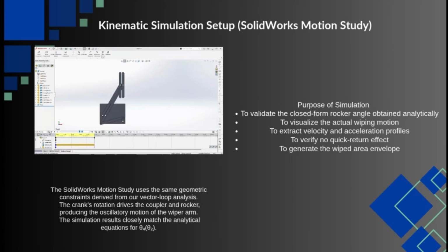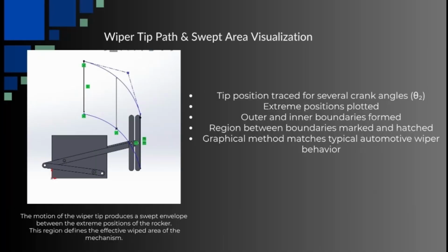The purpose of simulation is to validate our analytical rocker angle, visualize the actual wiping motion, extract velocity and acceleration profiles, verify the absence of quick return effect and generate the wiped area envelope.